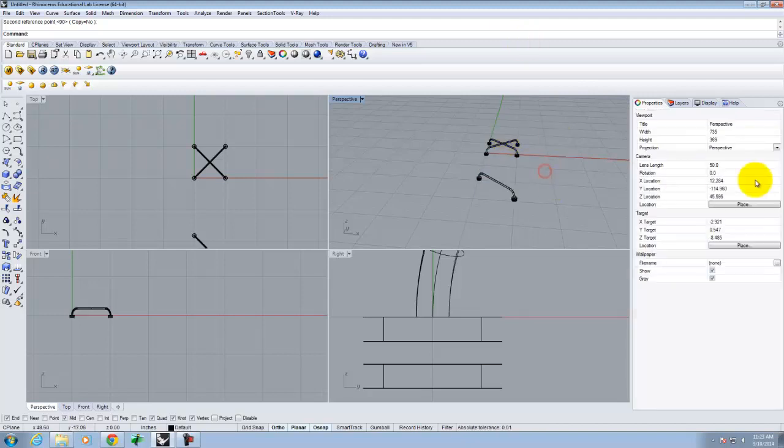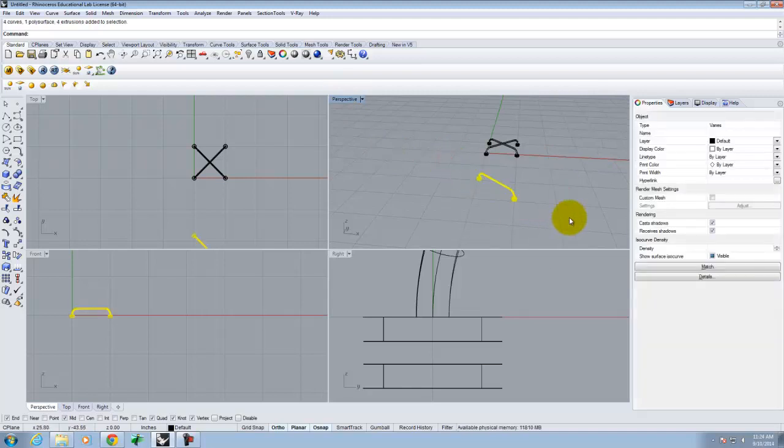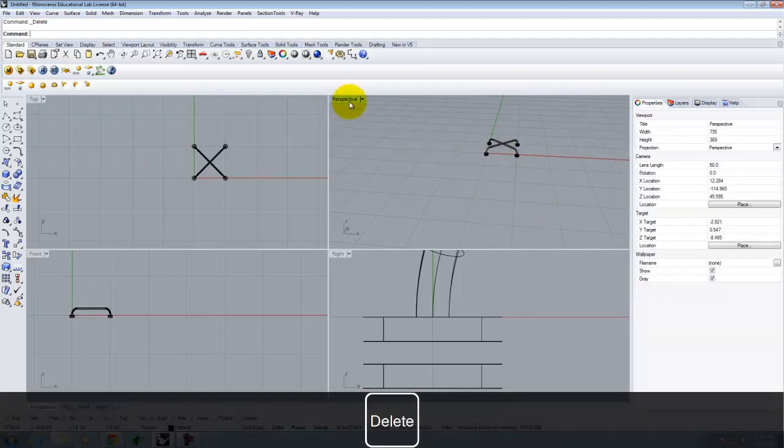As you get more and more efficient in Rhino, you'll start using things like copy in place and then rotate the last command. Rhino is very good at keeping things selected as you go through commands. So if you do it in the right order, and you learn that order, for example, if you do a trim and then you do a patch, you can a lot of times use the same curve for the trim and then follow it with a patch without having to reselect anything, which can be more efficient. So anyway, I've created those pieces, which gives me my little X.